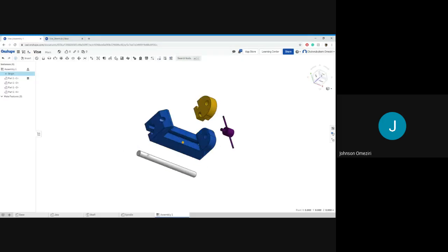So now that I have this here, I could add this. I want to create a mate relationship between these, so I'll use the cylindrical mate. The cylindrical mate is up here. So click on the cylindrical mate. Can everyone see where the cylindrical mate is? If you hover around it, it should say cylindrical mate.